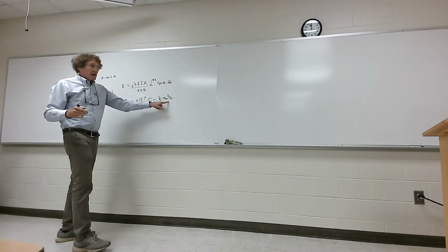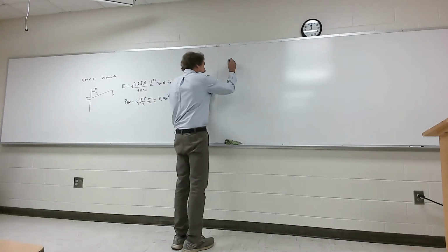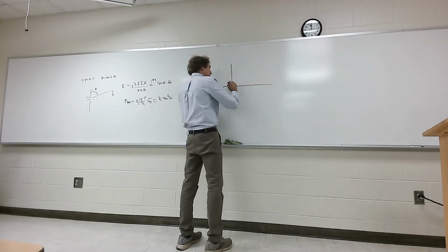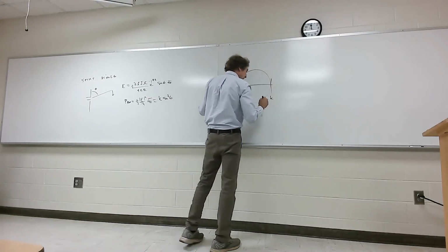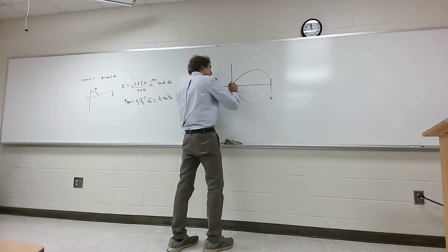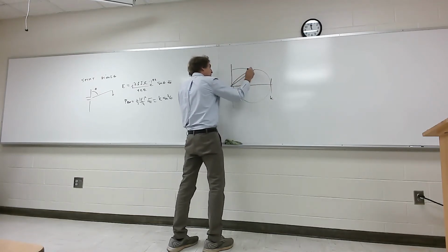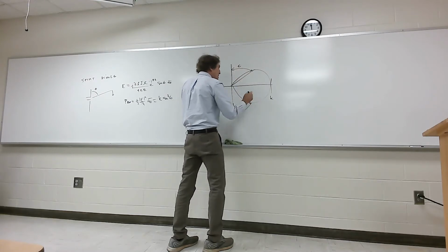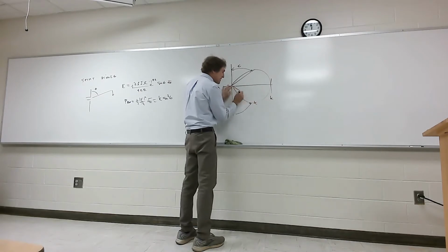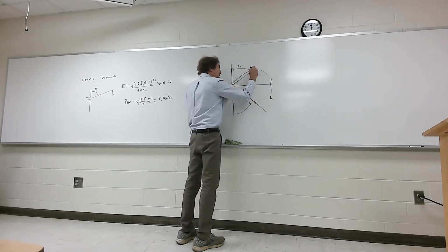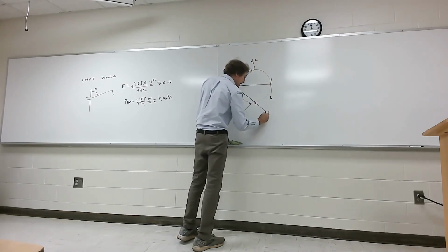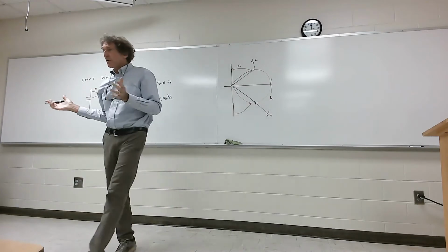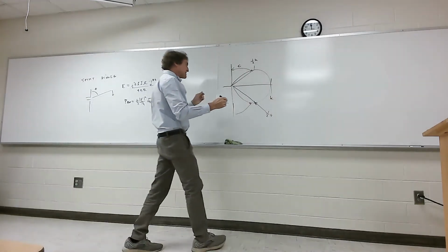Y'all follow me? Now, if you look at this and you were to plot this in a polar plot, it would look like this. You would have a maximum value out here of simply k, whatever that constant is, and there would be two points in this plot, from here down, where you would have a value that is 1/2 that value, 1/2 k. So it'd be right here, it'd be 1/2 k. It's half the peak power density. Y'all follow me? The beamwidth itself is this.